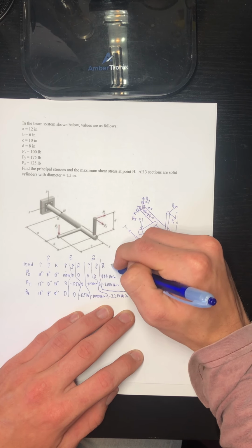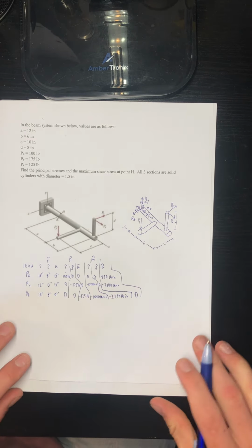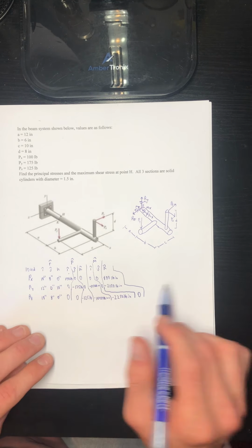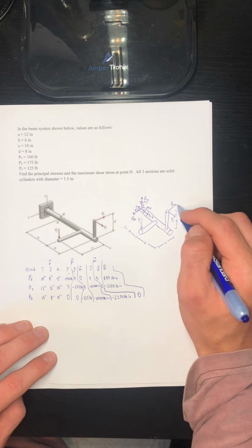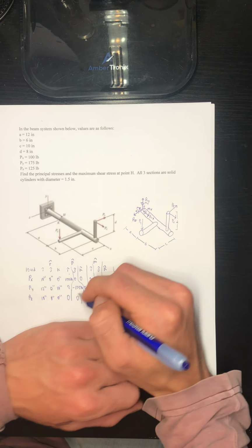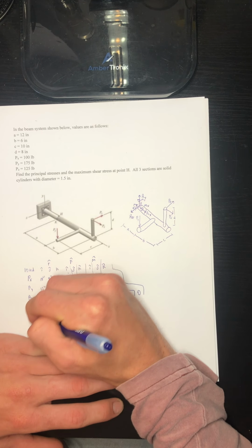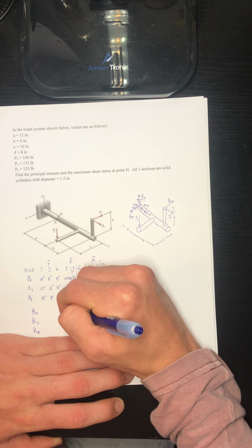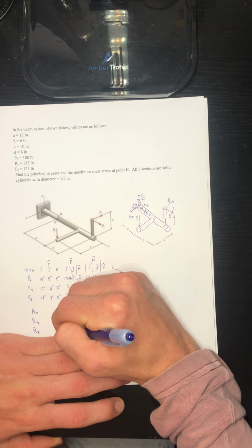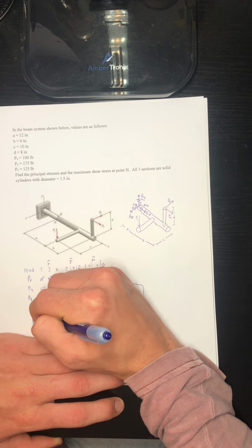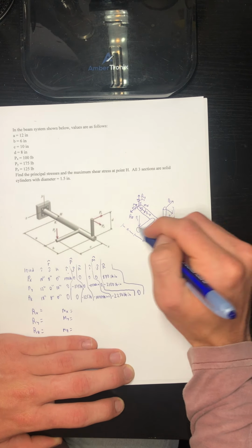And there is no moment resulting in the z direction. So I hope that you can see that. My apologies for not spreading it out, but here, nonetheless, are values that are resulting from these forces. So now we need to see what these reactions are as a result of this. We need to get a value for our x, y, z, Mx, My, and Mz. And whatever is going on inside of the beam needs to be counteracting these loads that are on the outside